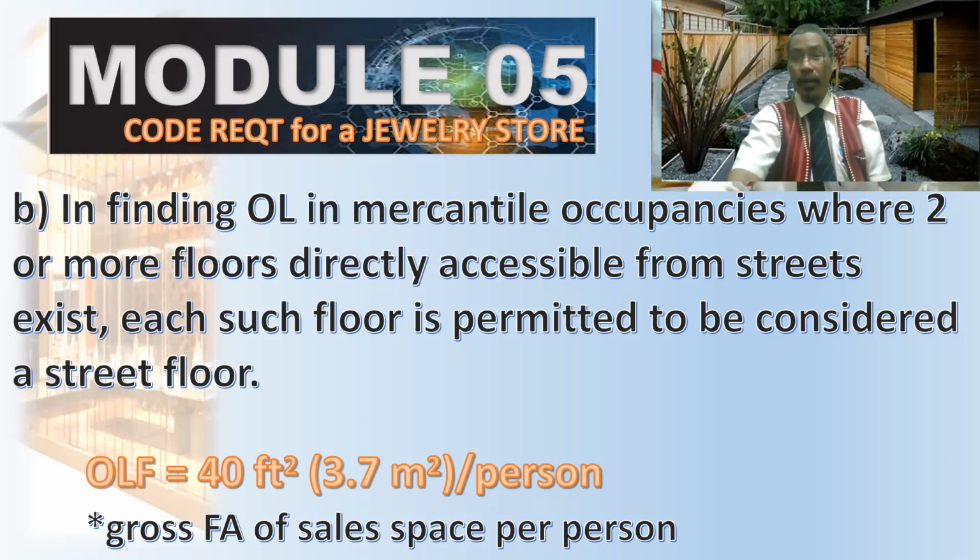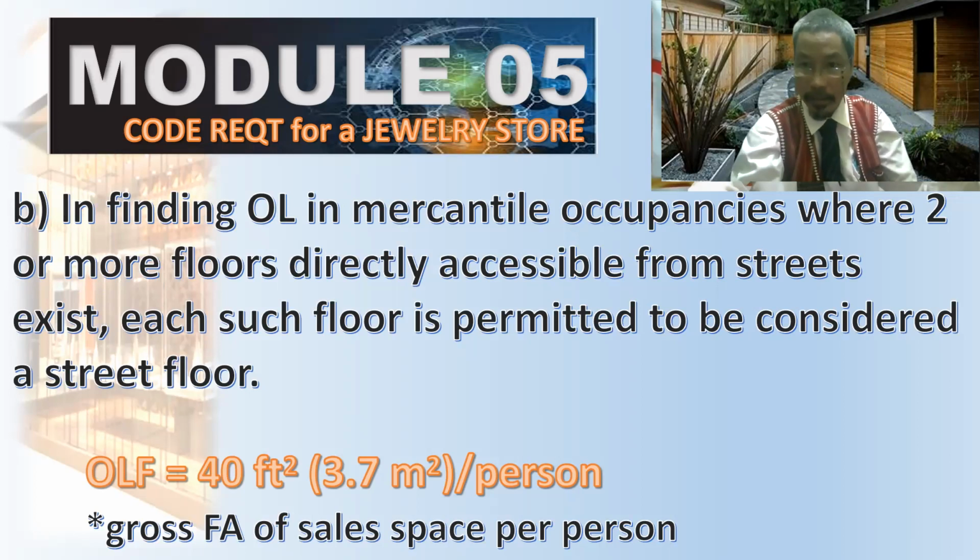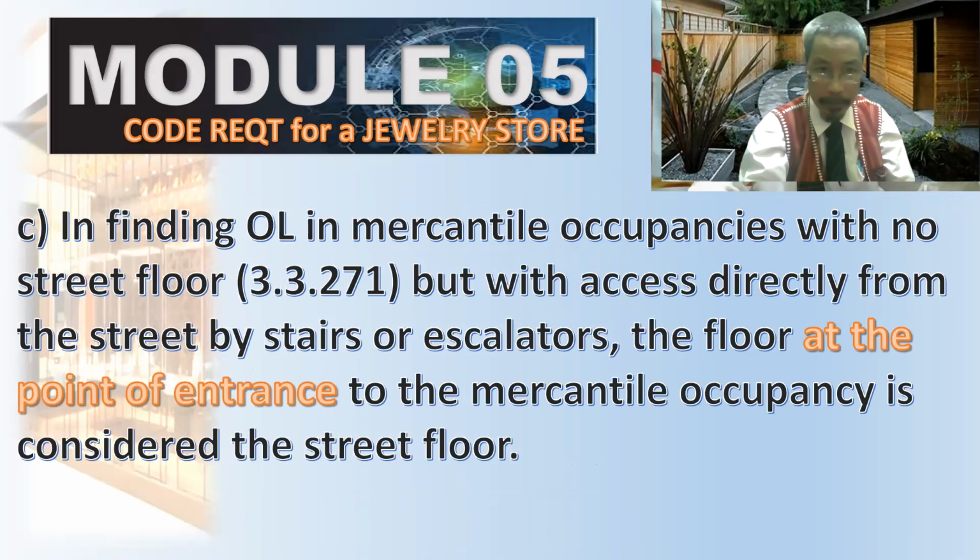Directly accessible from street exists. Okay. In finding occupancy load in mercantile occupancies with no street floor, but with access directly from the street by stairs or escalators, the floor at the point of entrance to the mercantile occupancy is considered street floor.